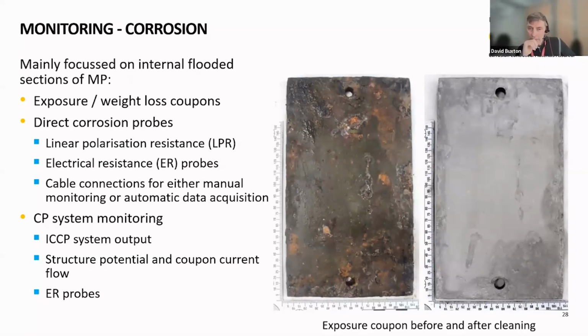The corrosion products seen on the coupon are very valuable, and so the sample should be preserved, and laboratory analysis can help to determine what corrosion mechanism is occurring, and detailed analysis can look at rates of localized corrosion and attack. There are some other methods for direct corrosion measurement. An electrochemical technique, linear polarization resistance, LPR, can be applied. So special probes are required, which would include a counter electrode, a working electrode, and a reference electrode. So a little bit more complex.